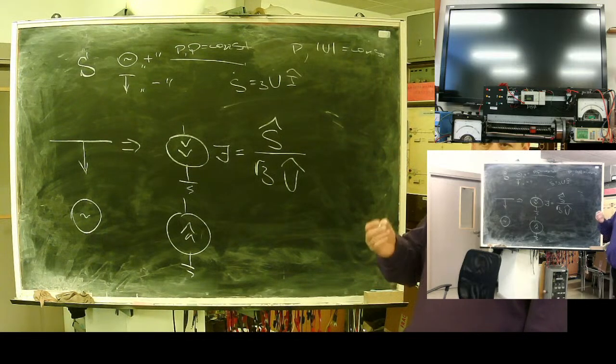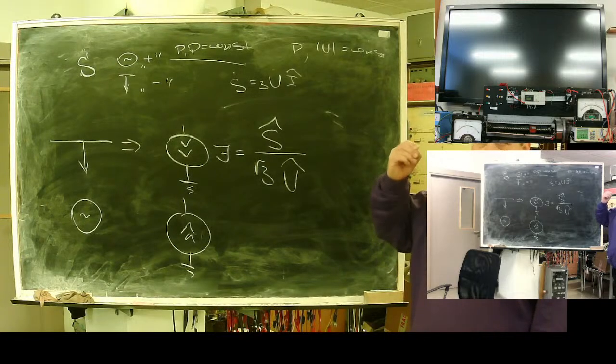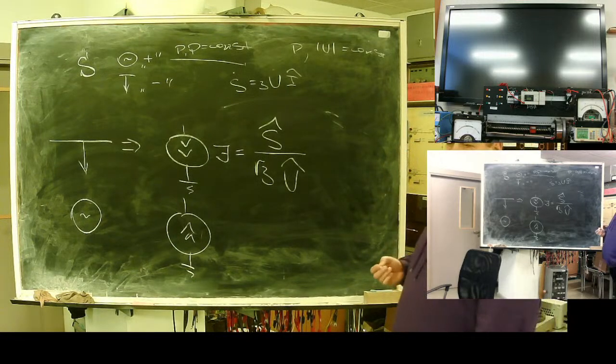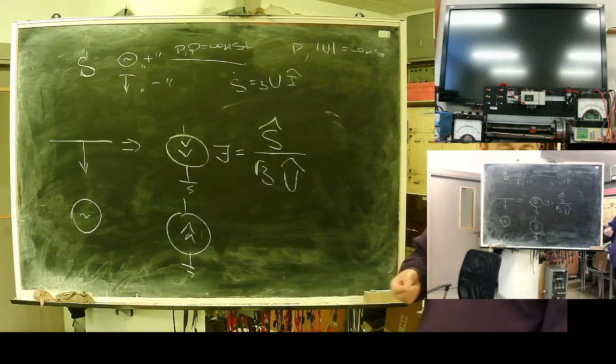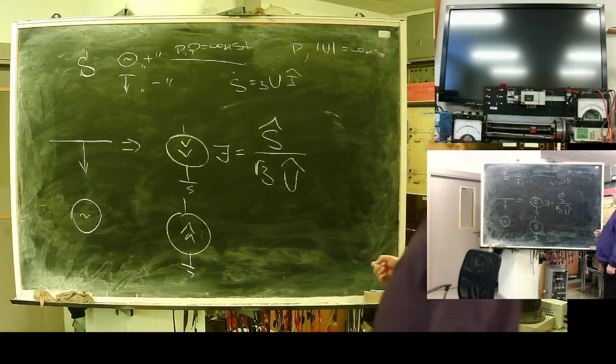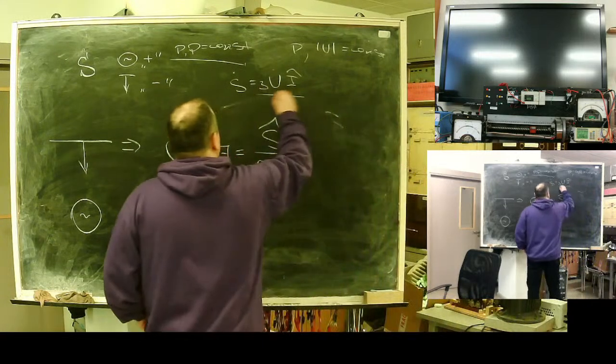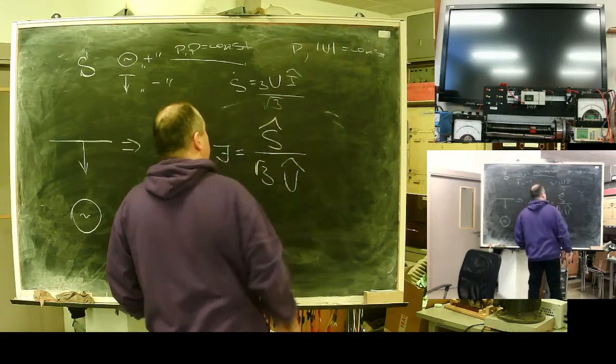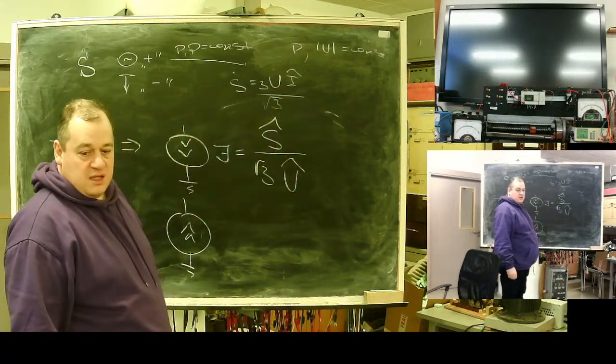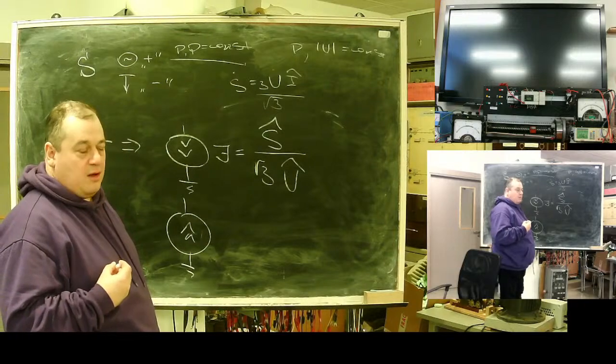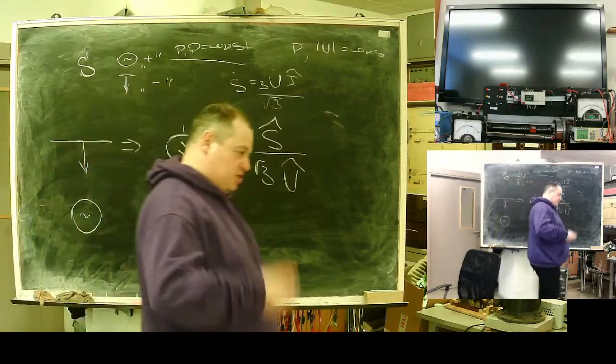But tradition asks to calculate for line voltage. 110 kilovolts is a line-to-line voltage. 10 kilovolts is a line-to-line voltage, not line to ground. If we use line voltage, we need to put a square root of 3 here. For calculus, we need phase. But tradition is tradition.